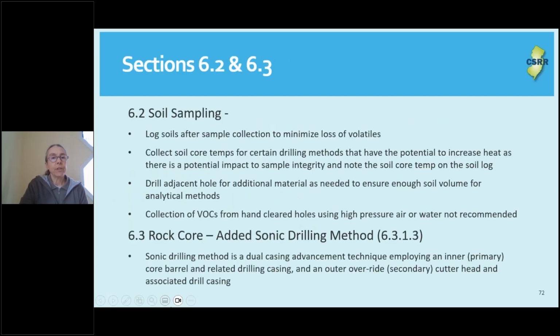Next slide. Section 6.2 covers soil sampling. There were no substantive changes to this chapter, but there were some things we wanted to highlight. First, it's recommended that you log your soils after you collect your sample to minimize loss of volatiles. If you're using a drilling method that has the potential to increase temperature of the soil core, it's recommended that you collect soil core temperatures and note those on your soil log.